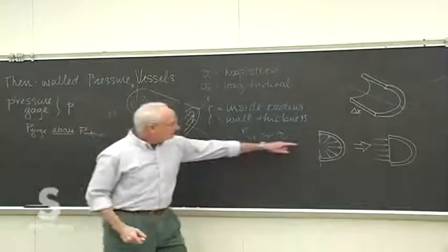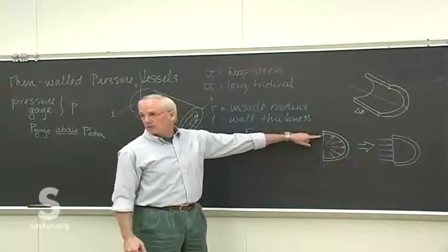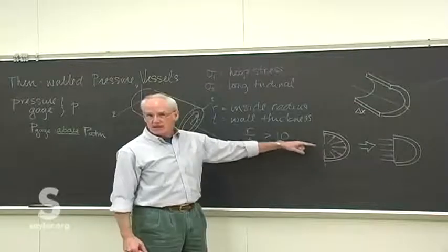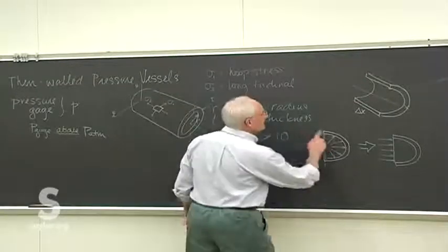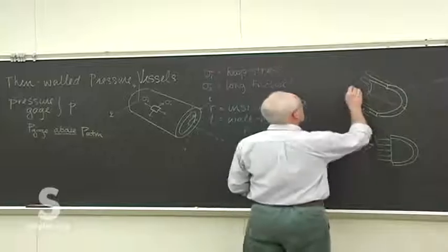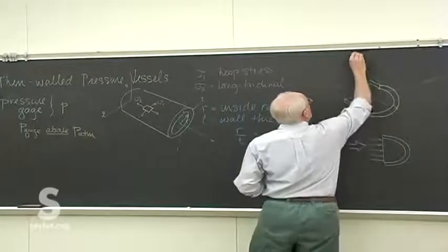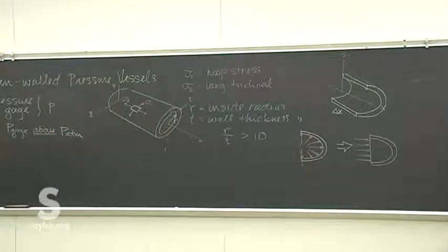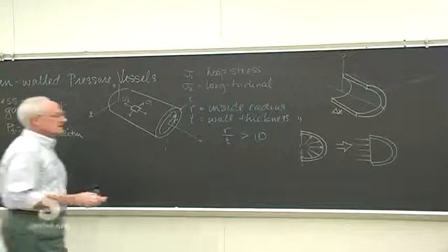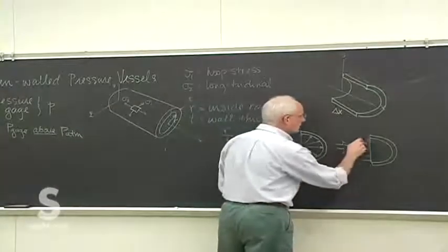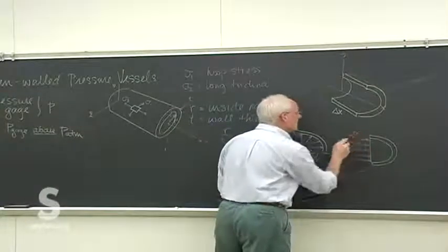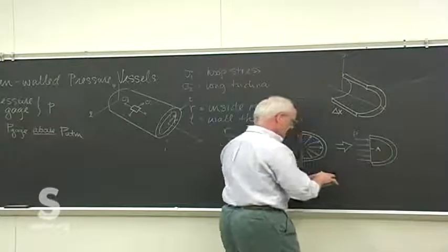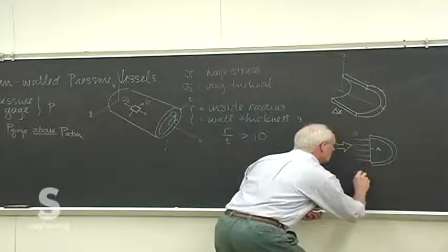This happens because every upward component of force has an equal and opposite downward component, and they all cancel. So any of the, let's see, this would be our y direction. Any y direction component to the forces cancel each other, and the result is that you only need to look at the equivalent pressure acting on a projected area to get the total force